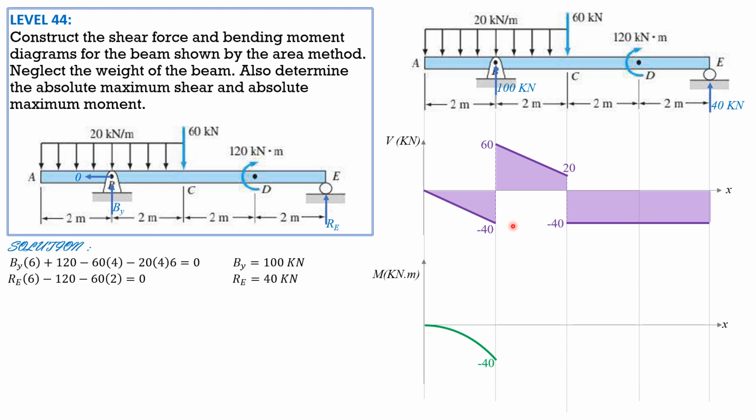This is from positive 60 slope to positive 20, so it is concave downward also, like that. Positive 20, positive 40 slope, concave downward. The area is 1/2 of 2, so 1 times quantity 60 plus 20, so 80. Negative 40 plus 80 is positive 40. Then the area of this diagram is negative 40 times 2, negative 80. Straight line, constant slope, but negative. So 40 plus negative 80 is negative 40 here.